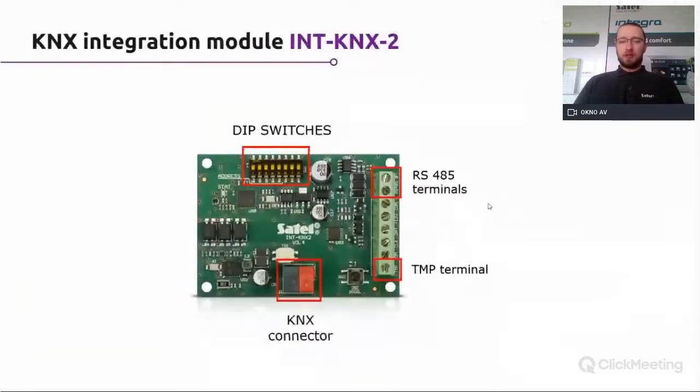In the right bottom corner, there is also a program button. Please remember, right now we are not using it, but later on, when we implement INT-KNX into ETS, you will need to use this button. For now, please don't use it. There is a small PROG LED at the bottom of it. It should be turned off by default, so for now you don't need to use it.